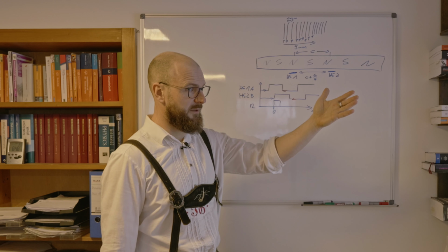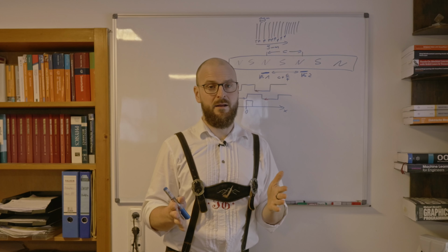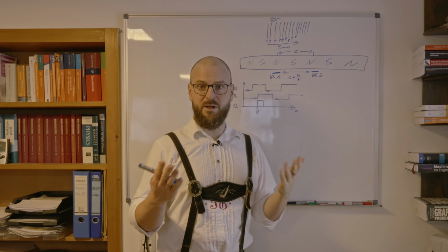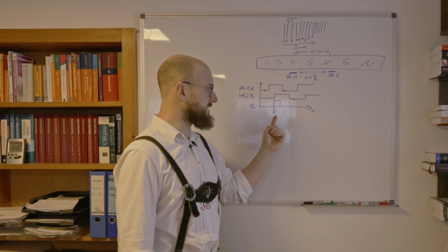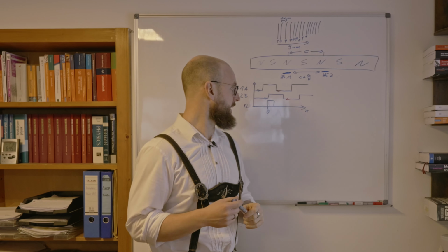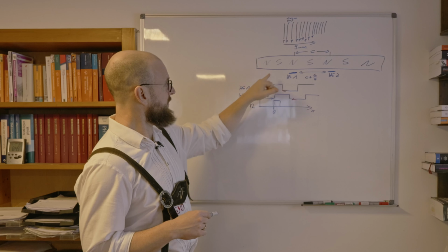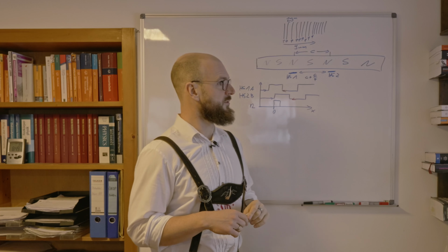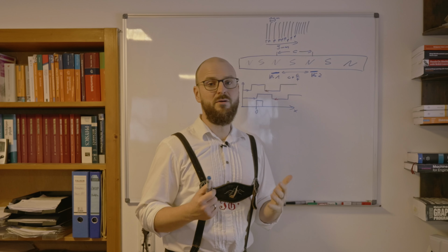Think of industrial machinery, which always needs you to do some referencing cycles at the start of the machine. That's the reason for it, because we have to find the zero for the incremental encoders. And one fact about the magnetic system, which is negative, would be the accuracy.